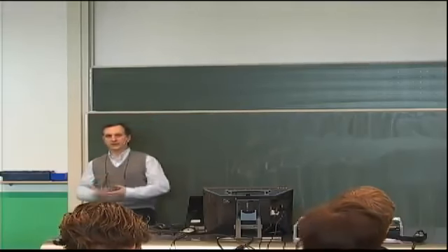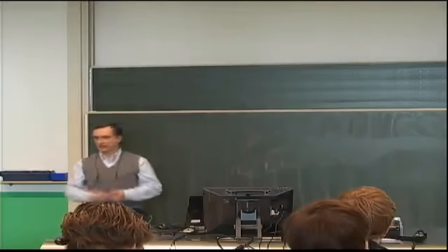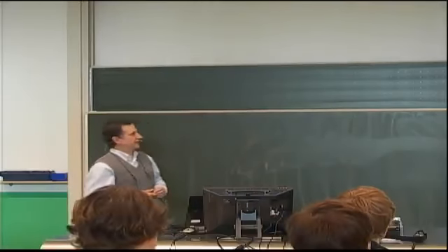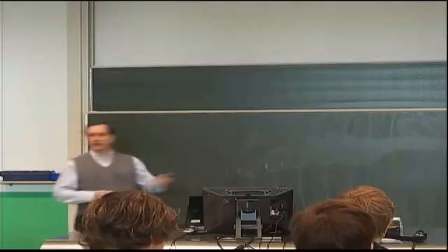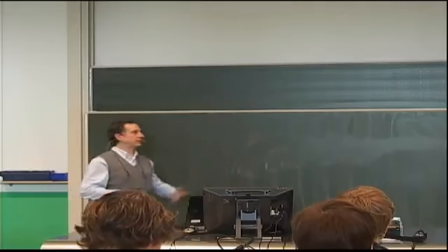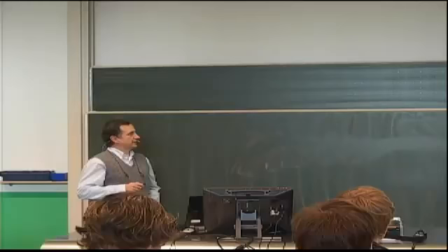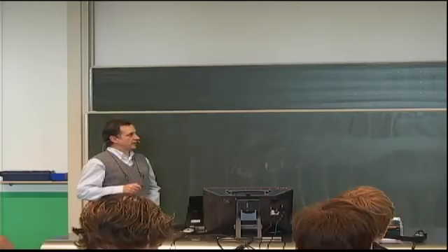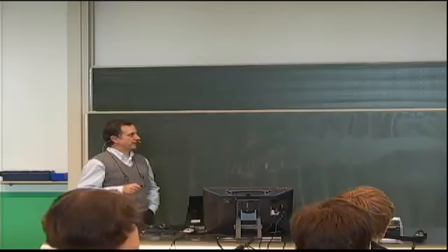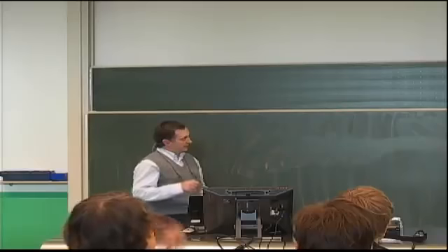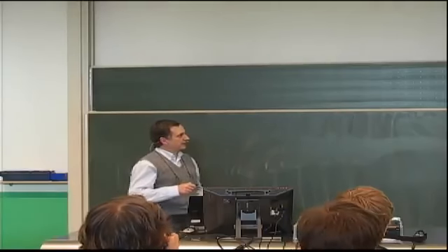And it would be necessary to come up with the reinforcements. So we're trying to see if through this solution we can at least get a feel for the size of these reinforcements. And after deriving the governing partial differential equation, we showed that the general expression is in terms of a Fourier cosine series here. And then using the equilibrium equations, we can determine the other stresses. And at this point, we had satisfied all the boundary conditions.